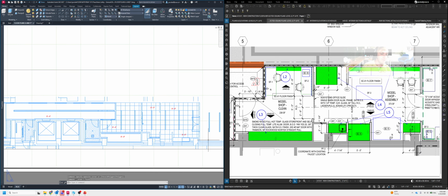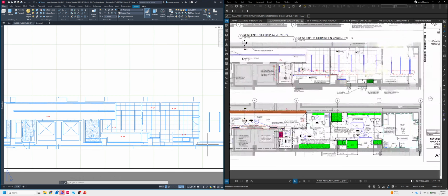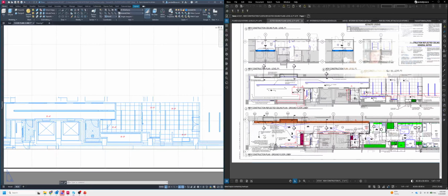But the other thing too is if you're looking for trim and where it belongs, the finished floor plan is where you want to go. If you're trying to find any trim callouts, the finished floor plan is going to be your key. It should tell you exactly which rooms get trim, and sometimes it may even tell you which walls specifically get trim.